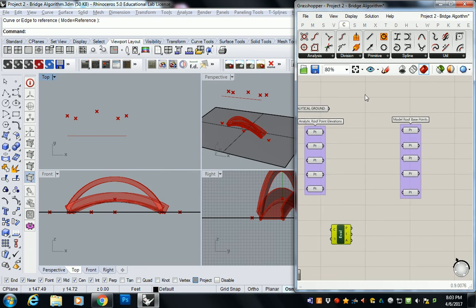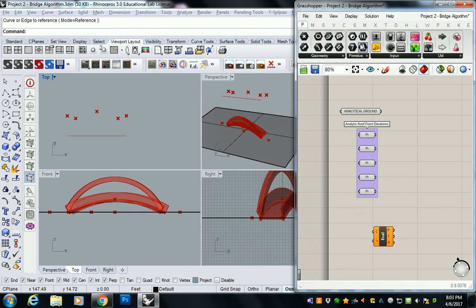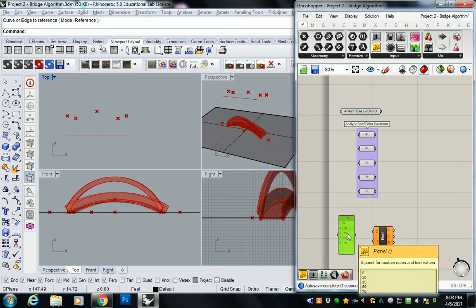All right, so this one's going to be a little bit weird, and you're probably going to have to revisit this one kind of cleverly. But we need to tell it how many feet it's going to measure to, and this is going to have to be on multi-line data. So our first distance was 0 feet from the end of the line. Oops, sorry. The next one was 10 feet. The next one was, let's see, it was plus 25, so that's 35 feet. And then 60 feet, and then 70. So that's all of the foot distances from point to point across the overall line.